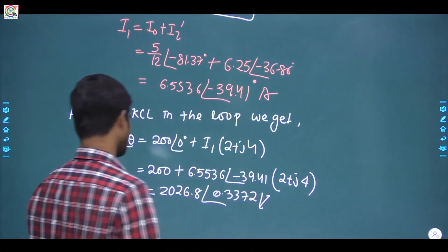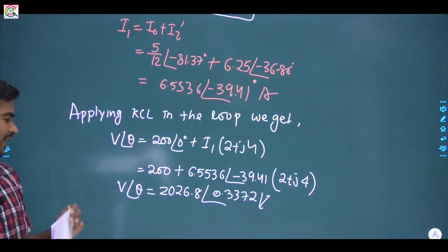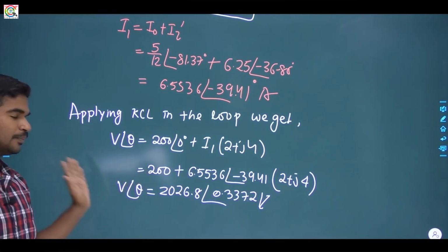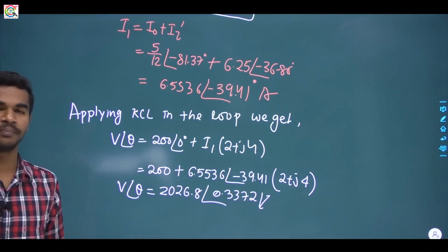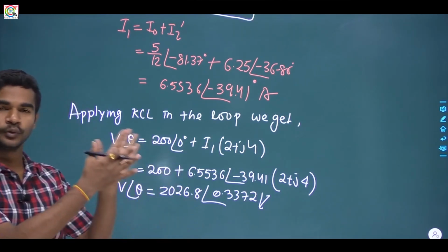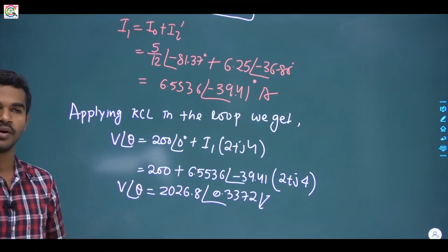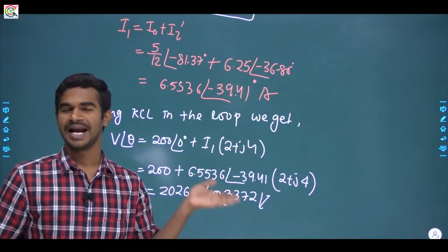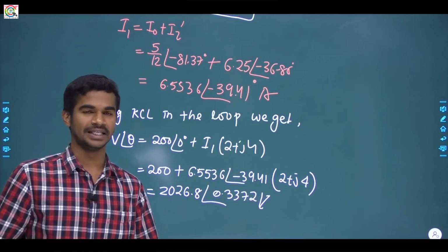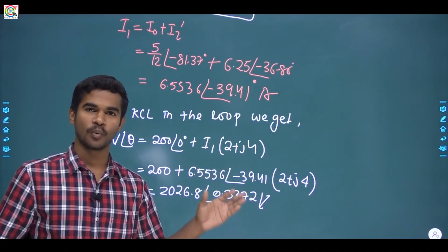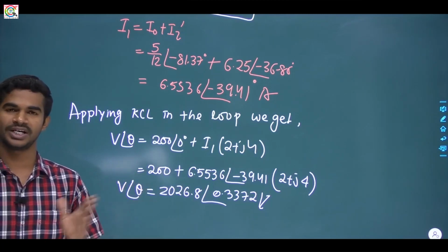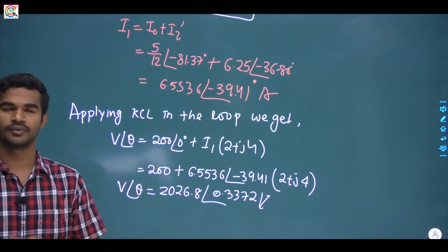Okay, so don't think that input side voltage or the supply voltage would be 2000 volt. No. Why? Because this is a practical transformer, and suppose the load is operating. First of all, tell me what is the rating of the LV side? It is 200 volt.